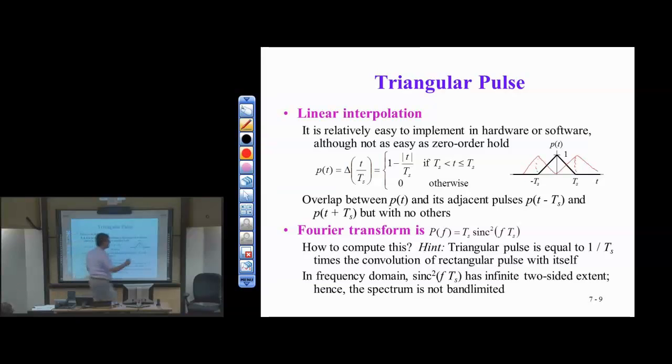So in other words, remember, what was the formula? The formula was flip and slide. So basically, for every sample, I'm going to flip and slide a triangular pulse in continuous time about each sample. So if I have 1, 1, 1 as my sample values, what I've drawn here, then the value at any point between 0 and TS is simply the sum of these two triangular pulses, which is just going to be 1, which makes sense. So if I have 1, 1, 1, the interpolation will just be all 1.